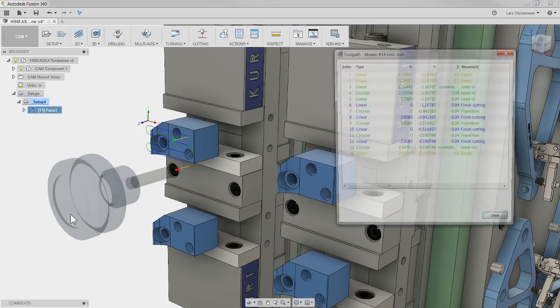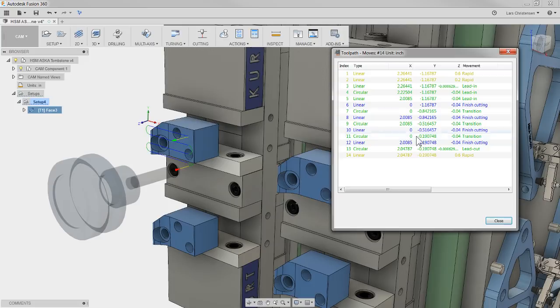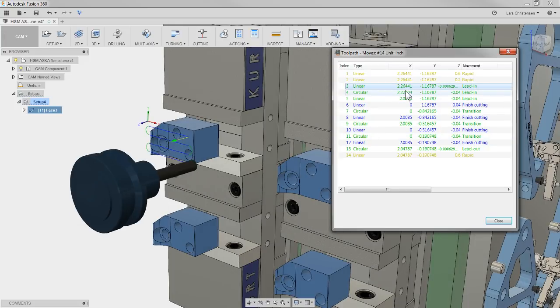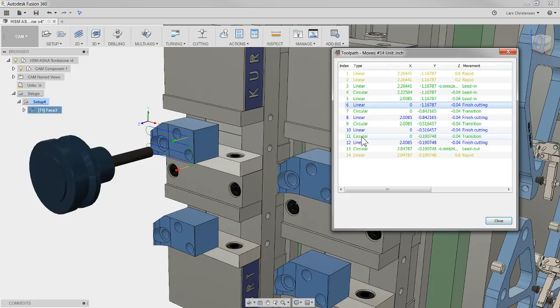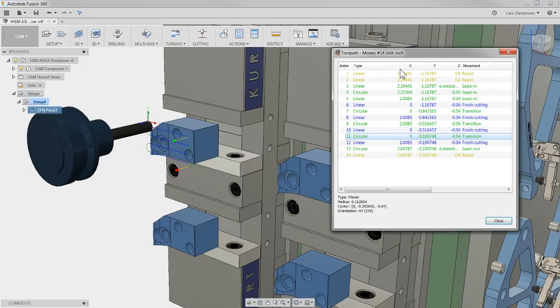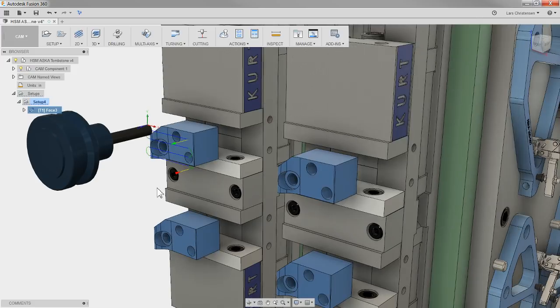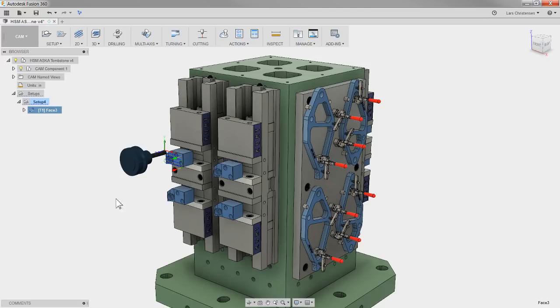Then we get this dialog up on this toolpath here, and we can click through the simulation, and you will see when we get down here to number 11, we got an X0, which looks about right, and Y is low just a tiny little bit. So that shows me that the outputted code is where G54 is, right on that stock point. So that's how you set it up if you want an individual stock.